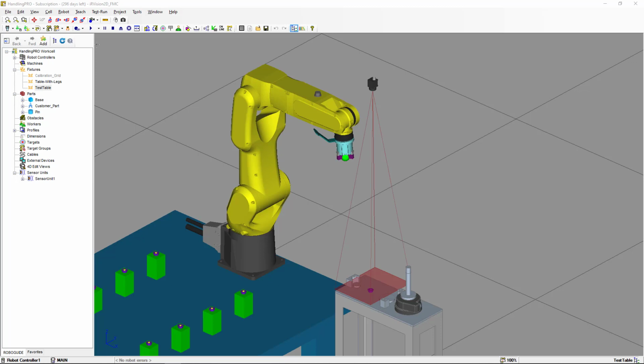In this video, I'm going to show you some of the fundamentals of camera selection, and we're going to look at the parameters that you have to consider when you select your camera and lens. One of the other important things is that the calibration grid that you're going to select for the camera calibration is going to be totally dependent on the size of the field of view of the camera. In other words, the size of the field of view dictates the size of the calibration grid.